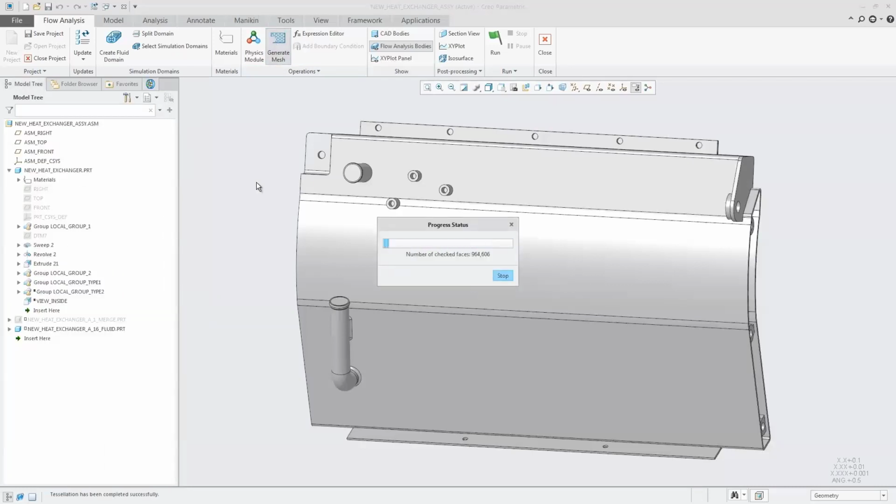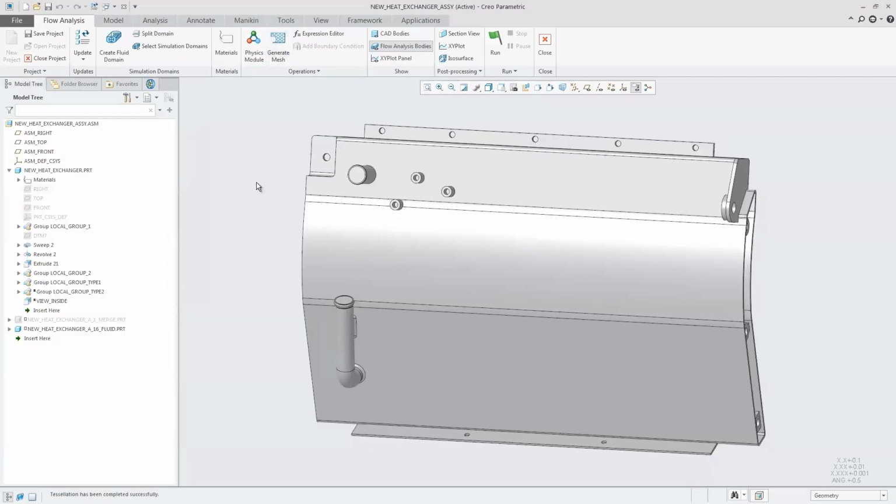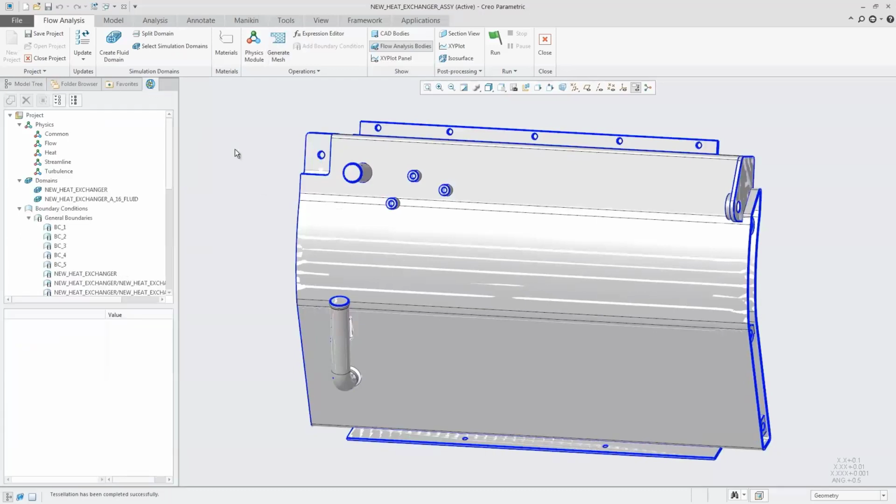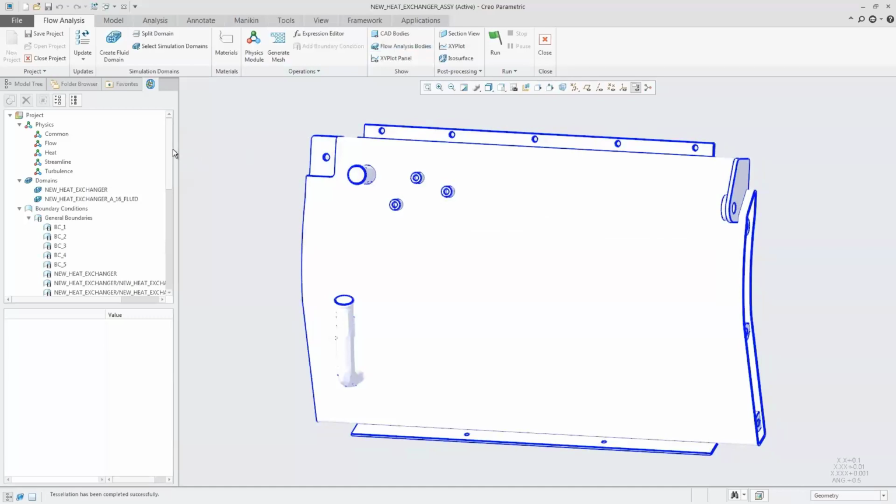Now, after putting in our initial boundary conditions and choosing what type of study we want to run, the next step is for us to set up or generate our mesh. Usually, this is a very important process when you're working with computational fluid dynamics. How do I want to generate my mesh? And how highly accurate do I want my results to be?